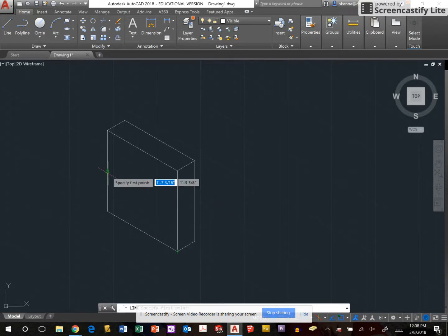I could also, if I have my midpoint snap turned on, draw from a midpoint to a midpoint and then use the midpoint of this line, okay? This does not work in the corner to corner method. If you were to use corner to corner, you would have to draw both lines in there and then pick their intersection, not the midpoint of either line. It is a slightly different spot. I'm going to do it this way. You can do it either way.